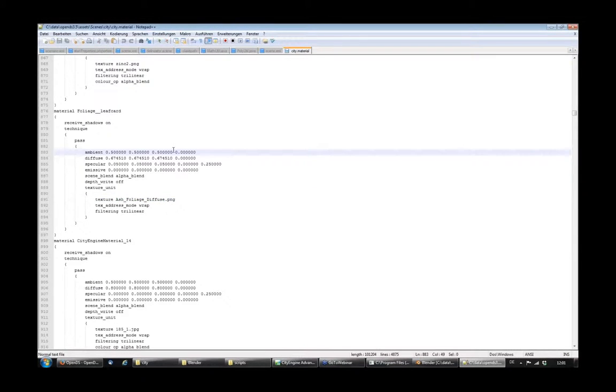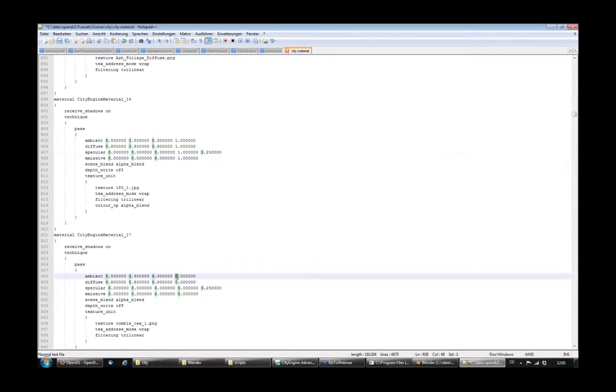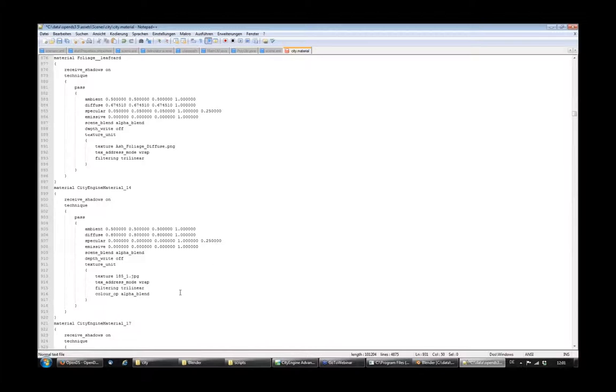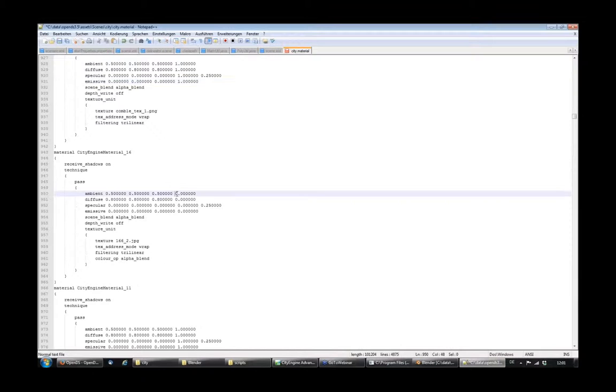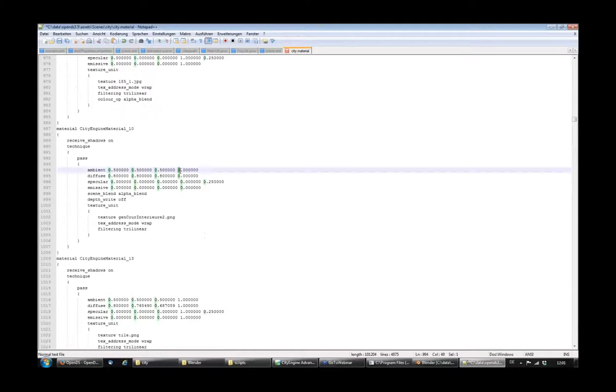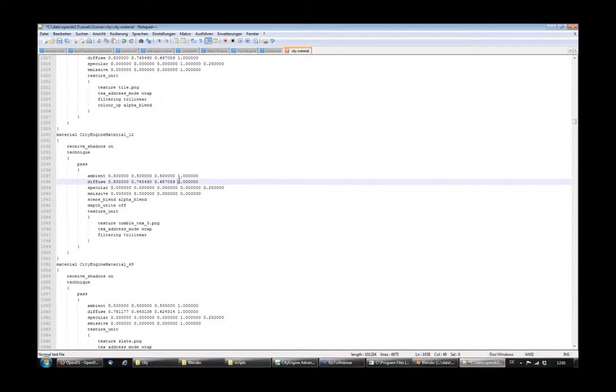As these seem to be invisible, we set these 4 values from 0 to 1. There are even further ones you have to set to 1, because 0 means that these objects are invisible. So it's quite a lot you would have to check here. Setting everything to 1 here will make objects visible again. So this happens sometimes when you export models, that there are transparency issues.